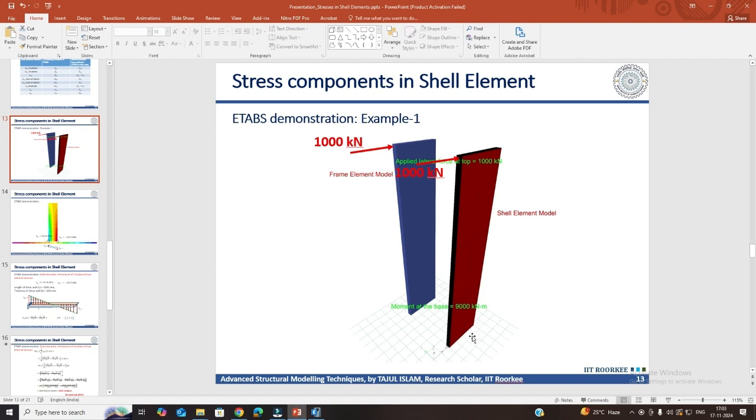But sir, can we design assuming there is a spring, and after that analyzing how much stiffness of the spring is coming, after that assigning the property? Yeah, that's what I'm saying. If you want to model a spring below this shear wall, then you have to assign the spring stiffness, and that you have to decide based on the testing on soil. So it cannot be predefined. There will be no predefined value. You have to identify that value and assign it to your model.